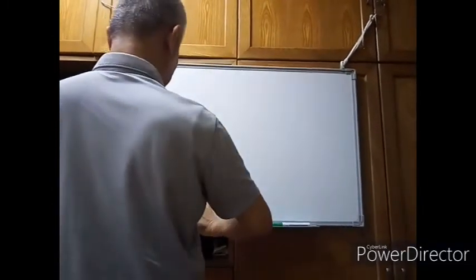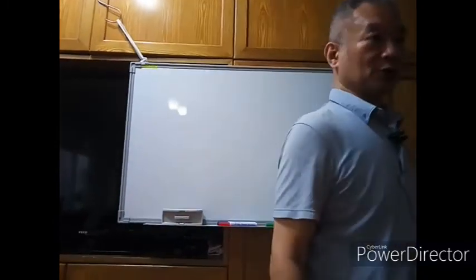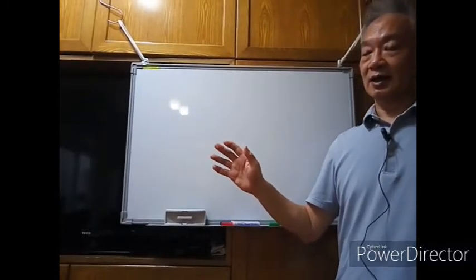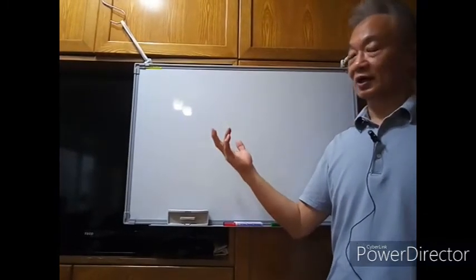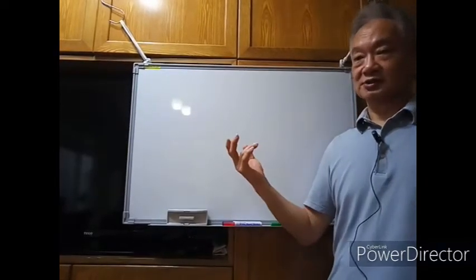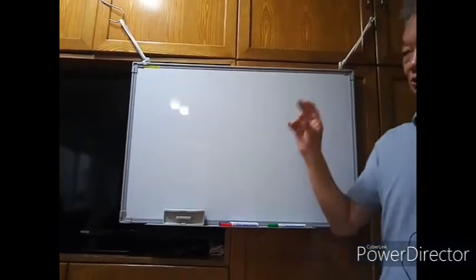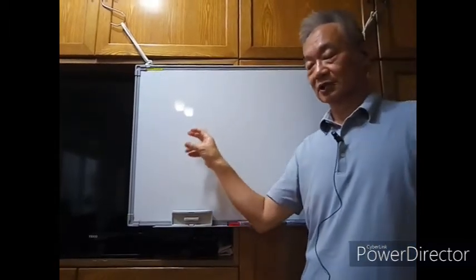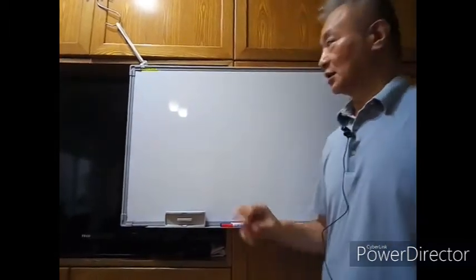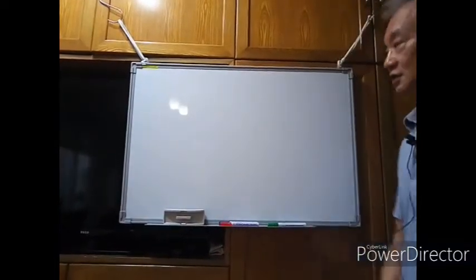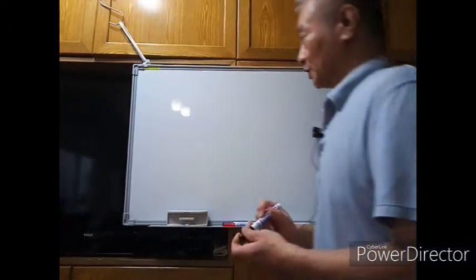Okay, so if the considered concentrated loads are applied directly to the nodal points, if you are the one who needs to develop the program, it is much easier to handle these problems. You just get those input data and put them to the correct positions in the load vector. So you finish the work. But if we have the